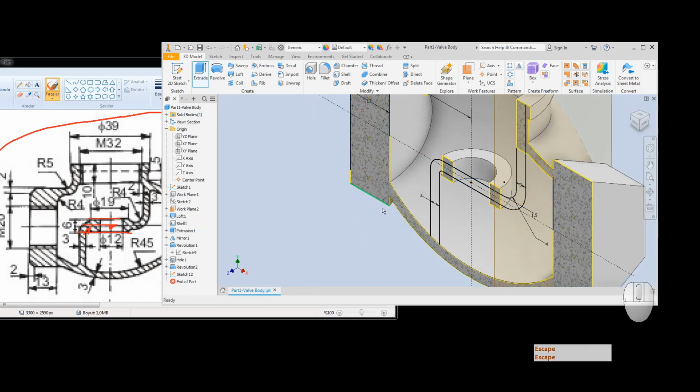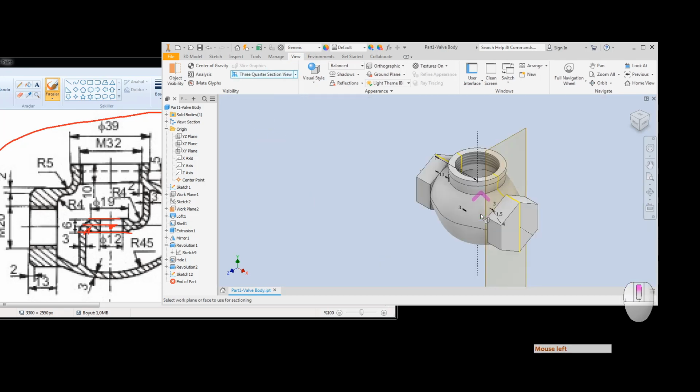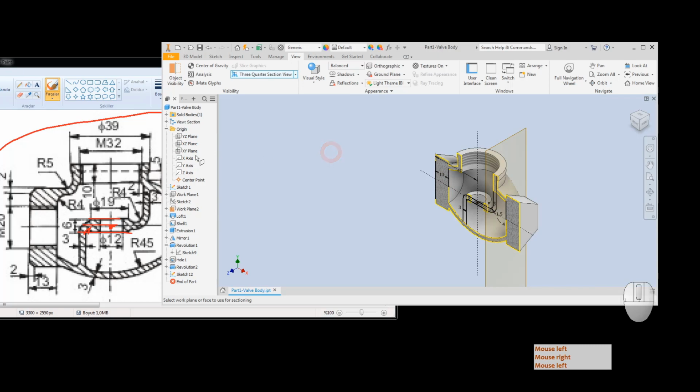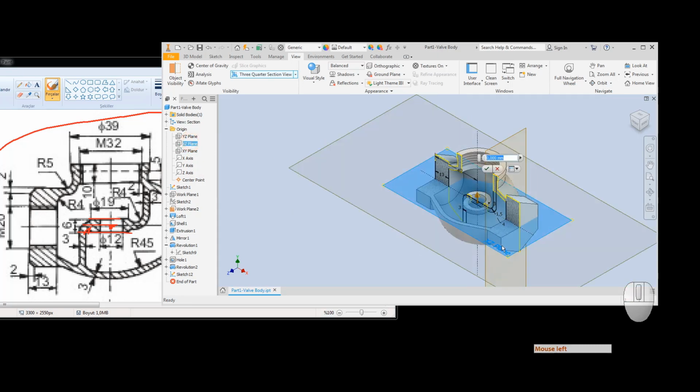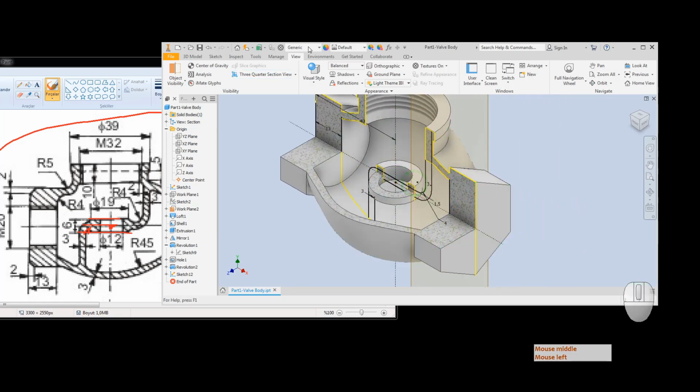What I did is I'm going to close the work planes, origins, to show you the view better in work. Okay, I have created the profiles. Also, I will need these sections to be extruded.